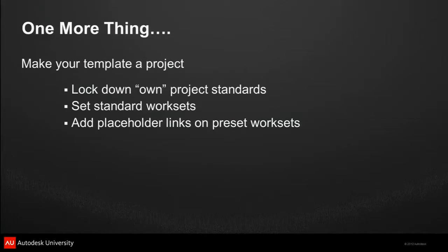Does anyone do that? Yeah, you take ownership of it. You can take ownership of those text styles and the dimension styles, and then they can't change them. You log in as admin, take ownership of all the project standards, save it, it's all set.